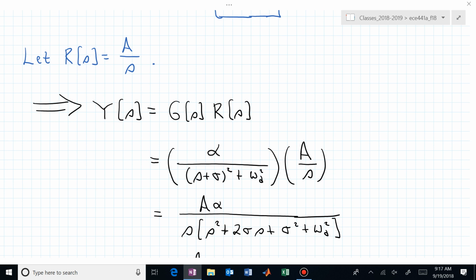And we will be playing now with this particular structure and seeing how we can use this parameterized form of the step response, capital Y of s, and connect it to the time domain expression so that we can make this connection between time domain data, experimentally measured points on the step response, and these parameters, sigma, omega sub d, and alpha.